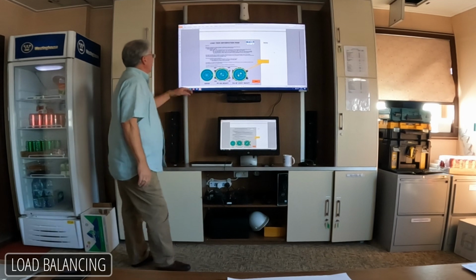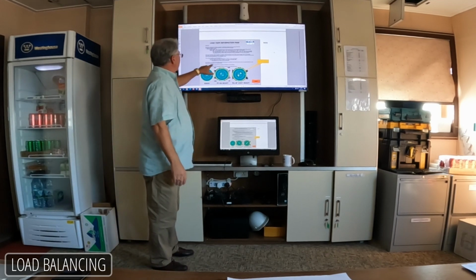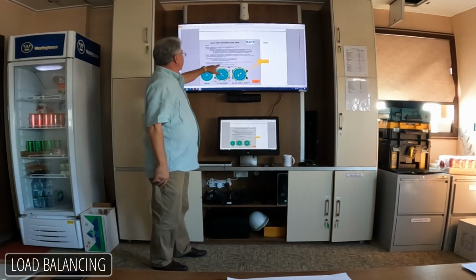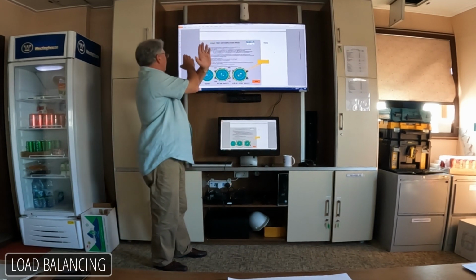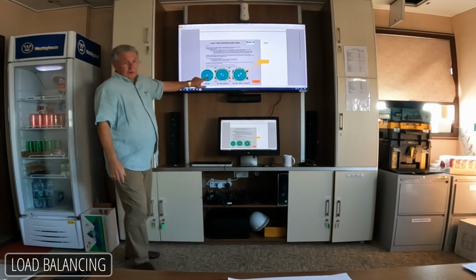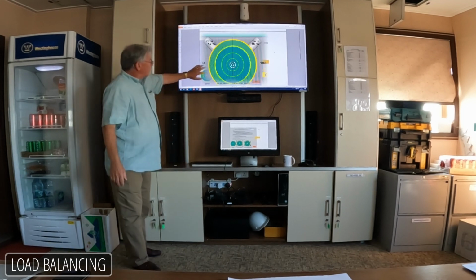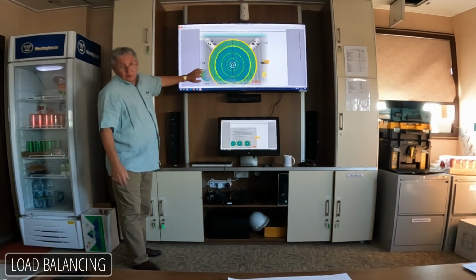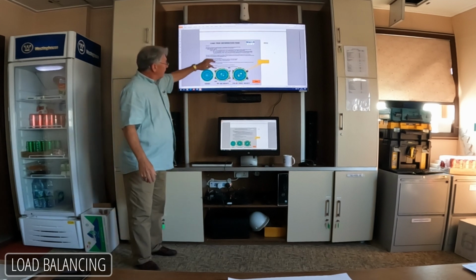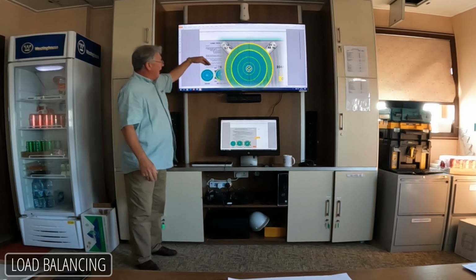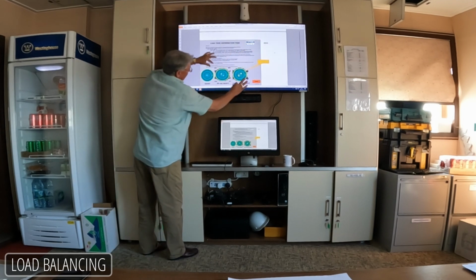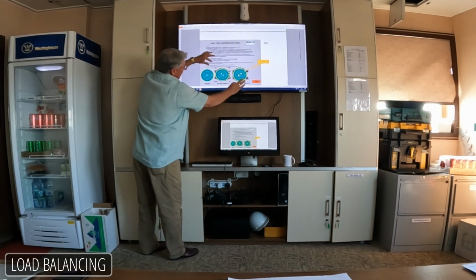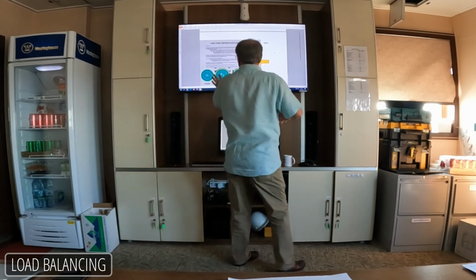Okay? In a perfect setup, all of the color discs on the snowman page are stacked up at the 0,0 location, and the diagonal graphic on the main operation page is all green, like this guy. This is a good diagonal balance. In this case, the port forward, starboard aft angle diagonal is starting to get heavy. This is a graphic that goes in and out on the heavy diagonal. So this is getting heavy.